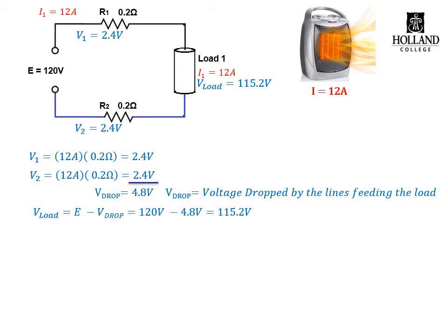This is one of the things we have to consider as electricians, is how much voltage are my feeder wires going to drop before I can actually use it at my load. We then have to compensate the size of the wires to reduce the resistance of the wires so that we reduce the voltage drop to maximize the voltage at the load. You have to consider the current or power of the load, because the more current a line draws, the larger the voltage drop on those lines. Let's carry on.